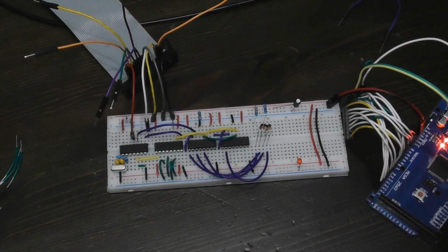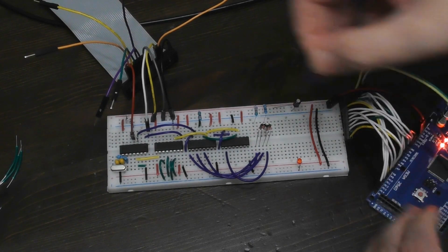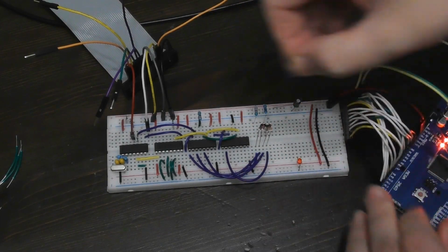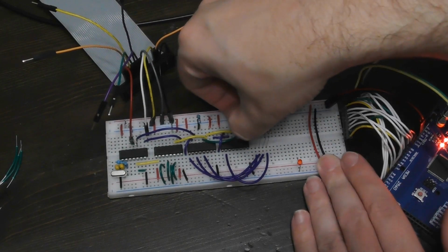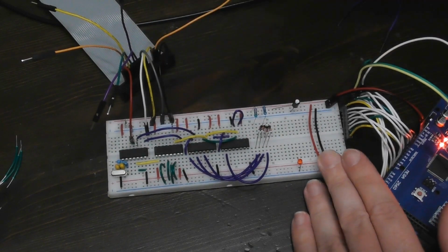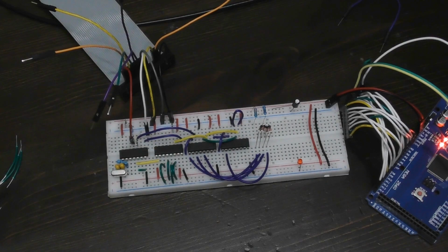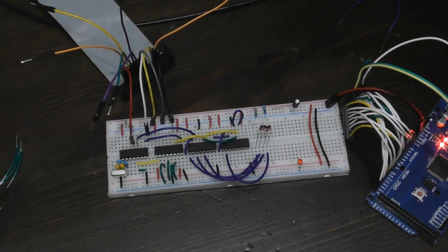Oh, the only other thing is I want the shift registers to always be clocking at the same time that they're shifting. So I'm just going to join the two clocks of the shift registers together here. And I can remove that pull-up resistor now. I'm not going to need that again. So now the shift registers are always clocking their output storage register at the same time that the shift register shifts, and I think that means it'll actually be 1 clock cycle behind, but that's not a big deal for us.